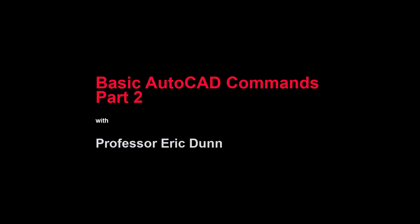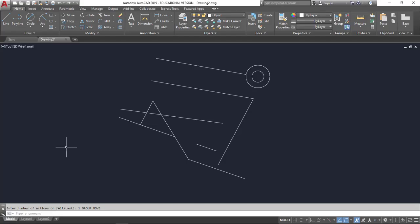This tutorial is the second part of basic AutoCAD commands in order to draw 2D architectural drawings. We're going to pick up where we left off with part 1. The first command I want to show is mirror. Anything that we've drawn, I'm going to click mirror.